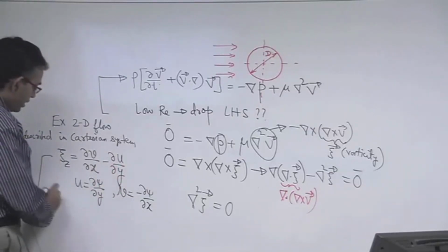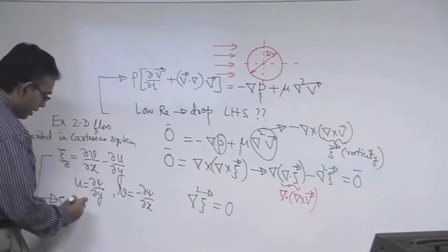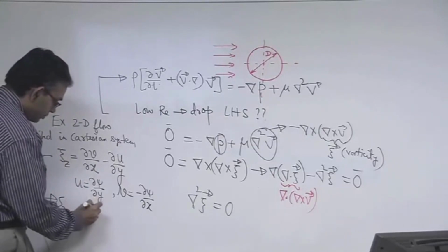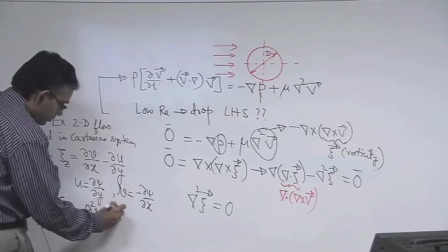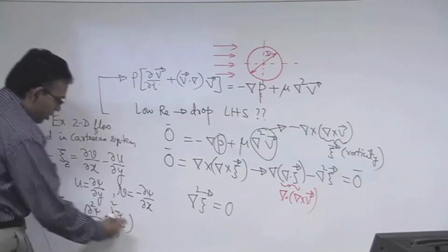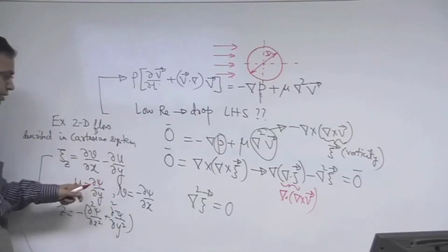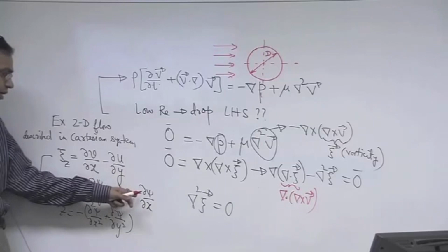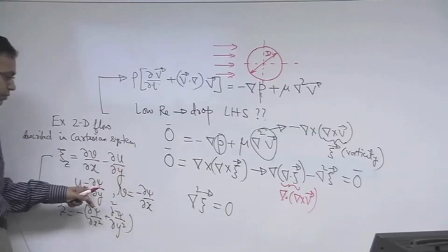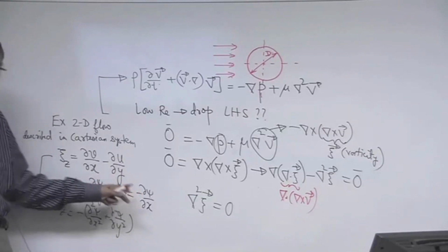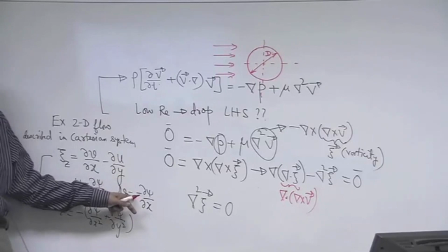So, you can write zeta z now. For defining the stream function, we have to be careful that u and v have to be carrying opposite algebraic sign. It does not matter, here we have taken this as plus, this as minus, but we could have easily taken this as minus and this as plus, that would have made no difference.